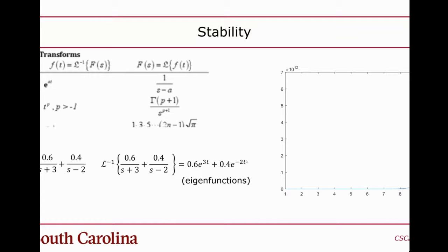Okay, so that is the inverse Laplace of the transfer function, but in particular, that's giving us the impulse response, because the original impulse was the input that we multiplied, and again, I didn't talk about that. I'll come back to that in a minute, but we basically multiplied the Dirac impulse with this. So we end up with this function. Then you just plot this function over time, which I did here.